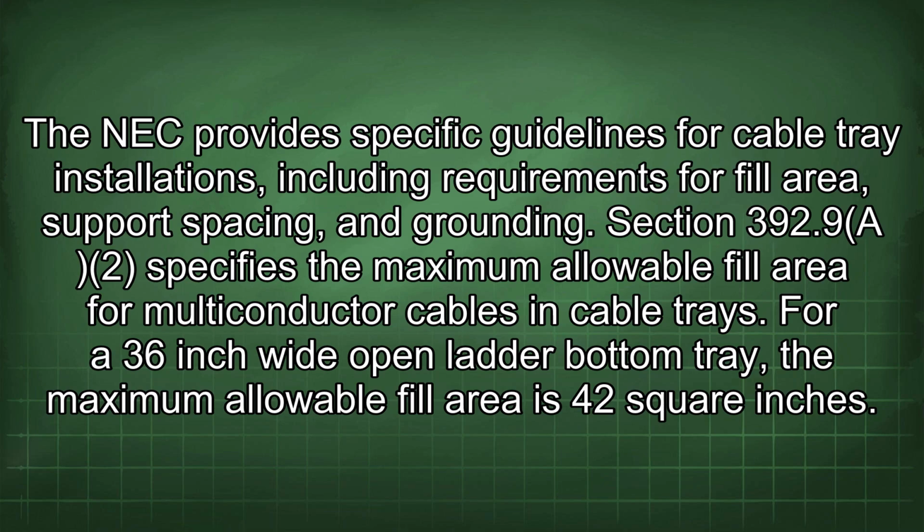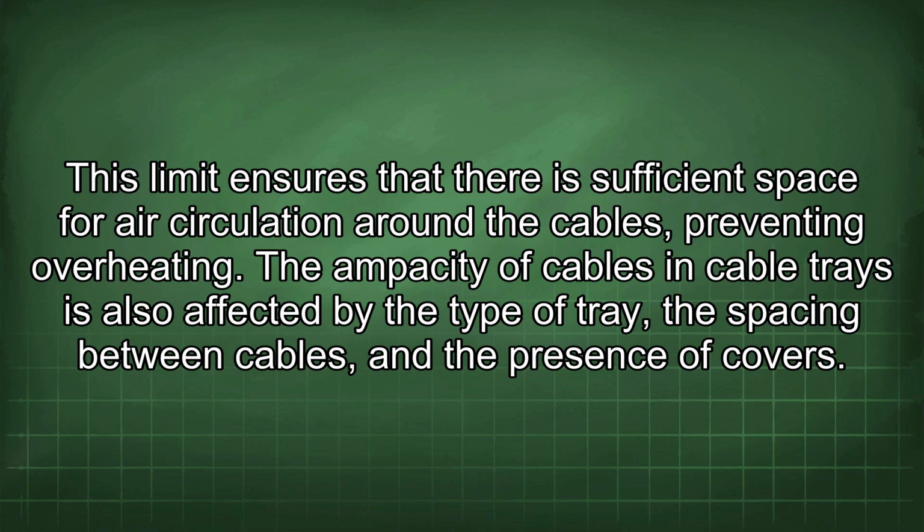Section 392.9 of the NEC specifies the maximum allowable fill area for multi-conductor cables in cable trays. For a 36-inch wide open ladder bottom tray, the maximum allowable fill area is 42 square inches. This limit ensures that there is sufficient space for air circulation around the cables, preventing overheating.